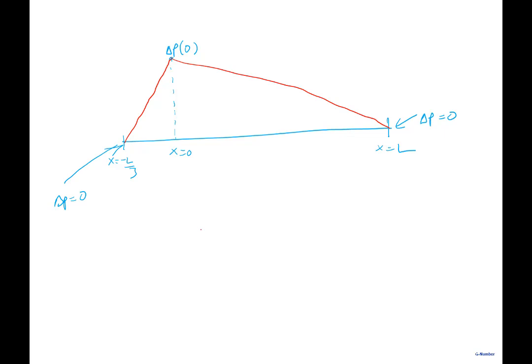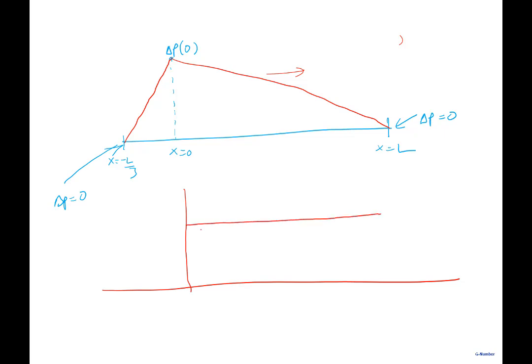How will delta n go? By the way, if you write delta P0, what would be the current then? How will the current go? Jp. How are the holes diffusing? From delta P0, holes are diffusing like this. So what is the amount of current that you get? You will get a constant current, equal to q Dp delta P0 by L, a diffusion current.